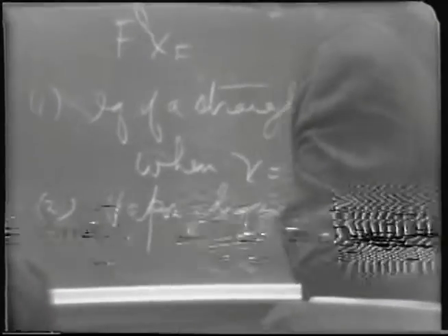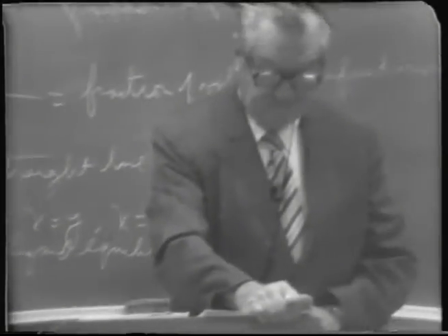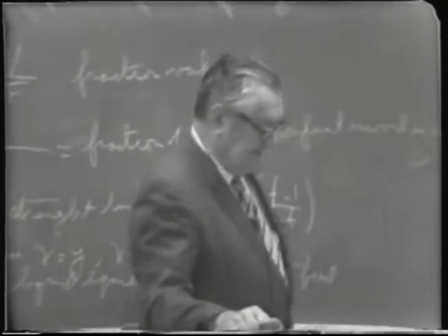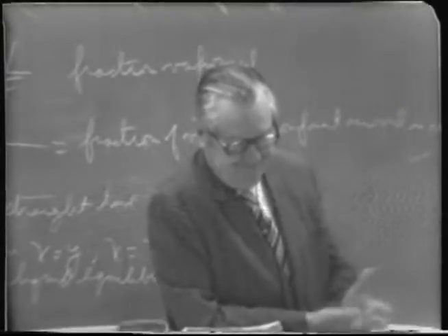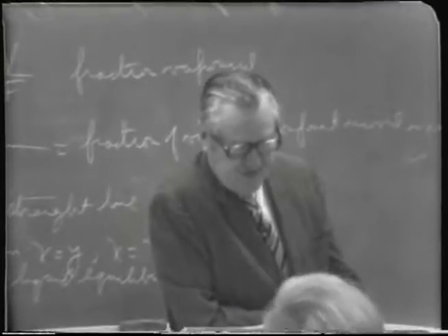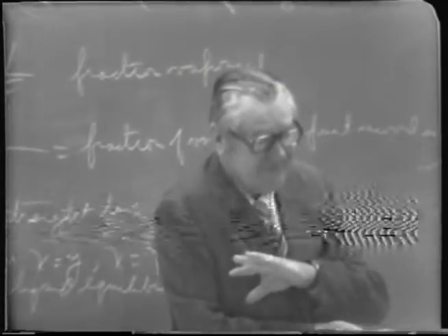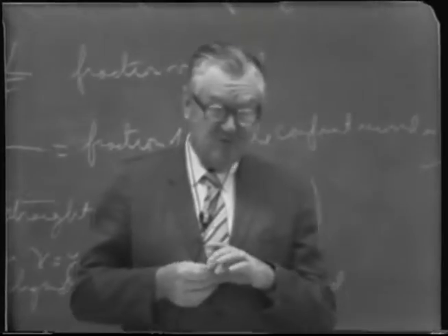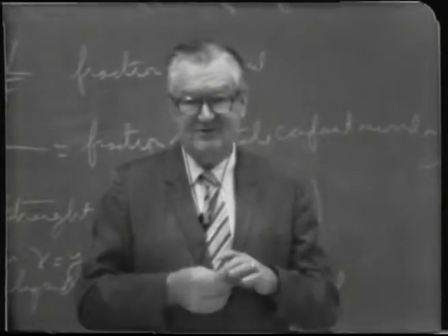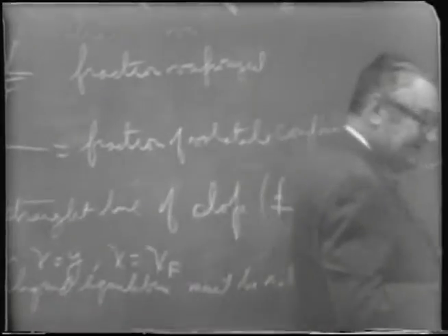Well, in the usual case, of course, vapor-liquid equilibrium is available or presented in the form of tabular data or graph. Most often the tabular data is not capable of being expressed by an algebraic equation, so we express it by plotting it as a graph.